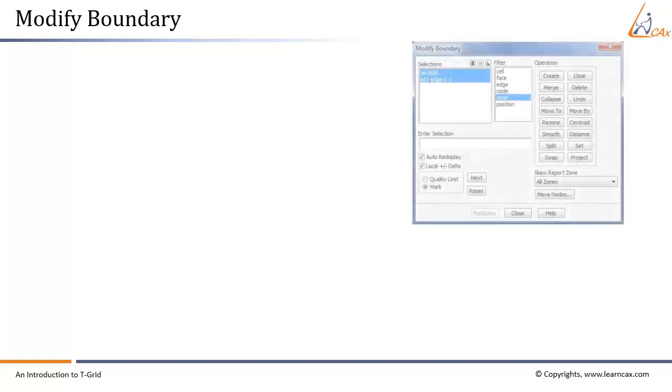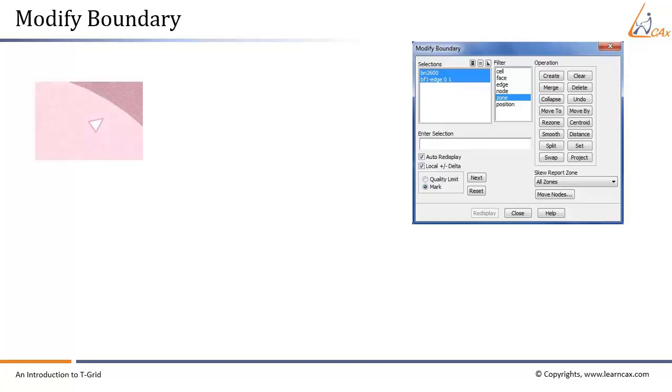Now, let's consider the different types of boundary mesh repair operations. In this step, you will recreate the missing faces to repair the boundary mesh. Let's have a closer look into one of the missing faces. The faces surrounding the missing face can be highlighted to enable easy identification of the missing face. Enable Free in the Options group box in the Display Grid panel to highlight the faces surrounding the missing face.